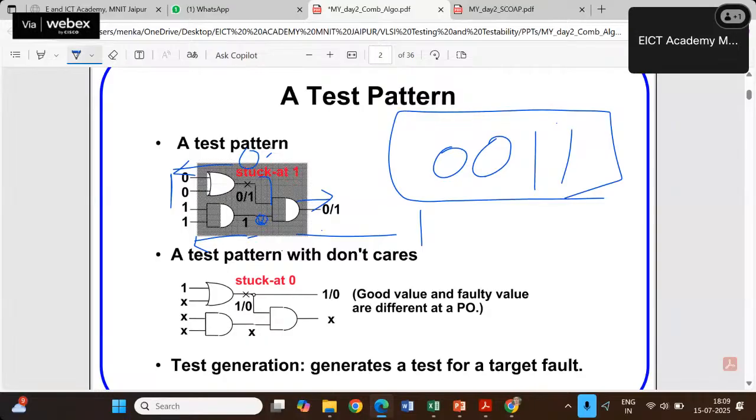So let us proceed now. This exercise is going to keep in mind what should be the backward implication, what should be the forward propagation of the fault at the output, and all these things. So if we want to simplify it, just find its truth table.